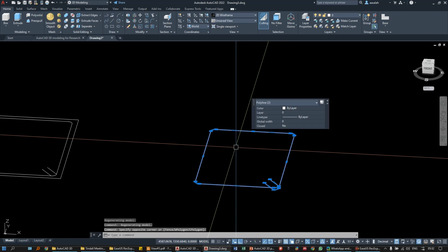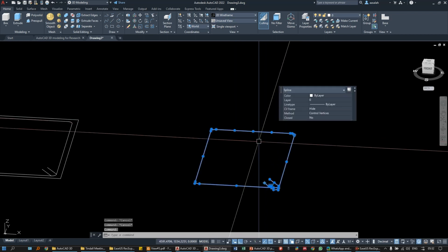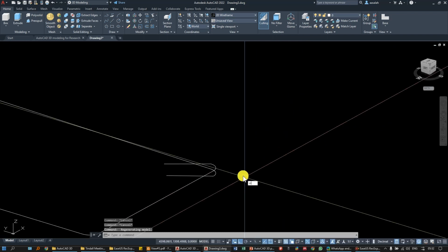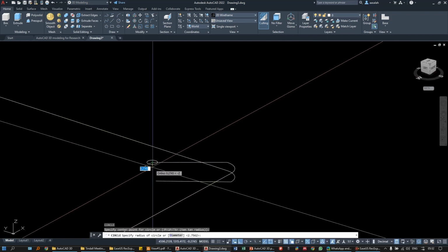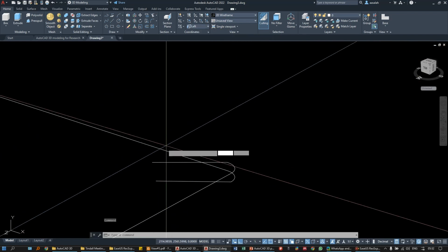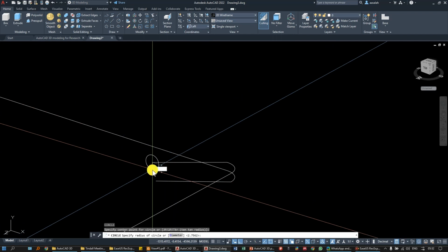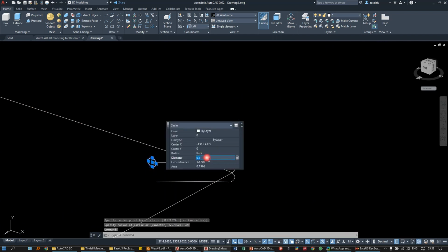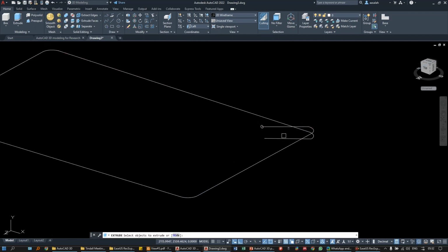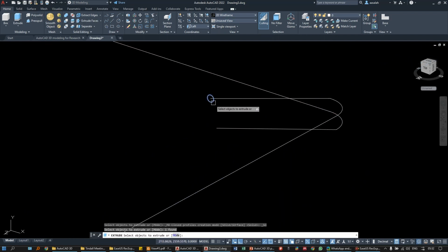Now it's one line. Let me try now. I'm gonna select the cross section of this stirrup, which is, I'm gonna work on the left direction. The stirrup diameter is 0.25. Yes, so I have this cross section. I just extrude it, select this cross section, and then select the path, which is this one.